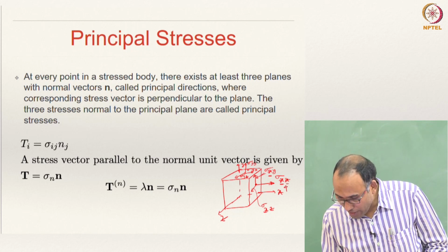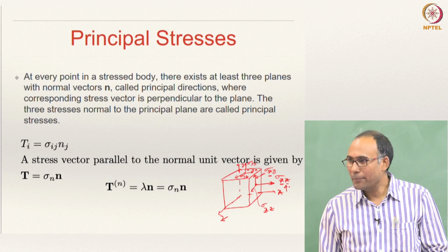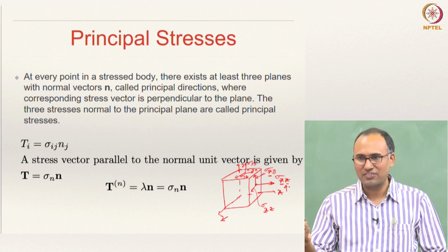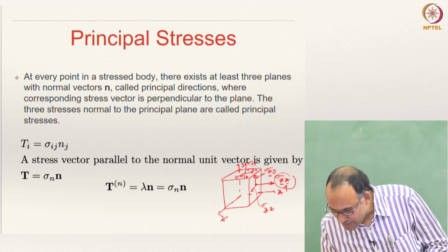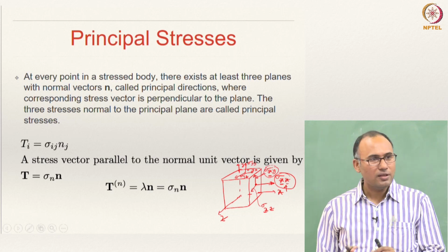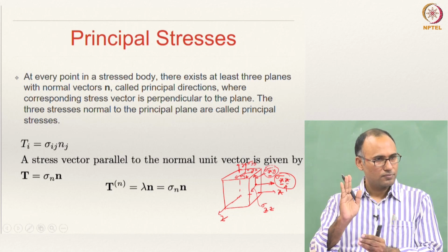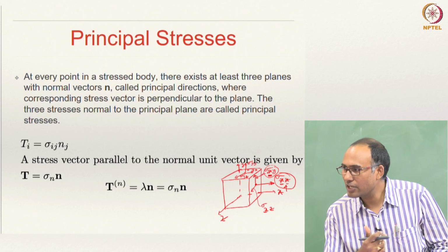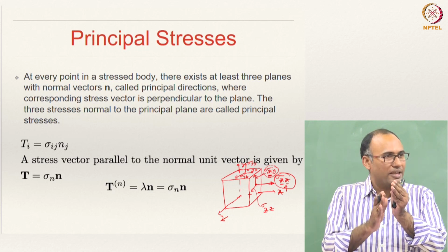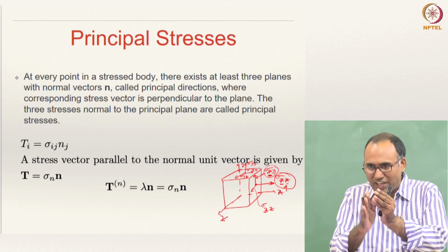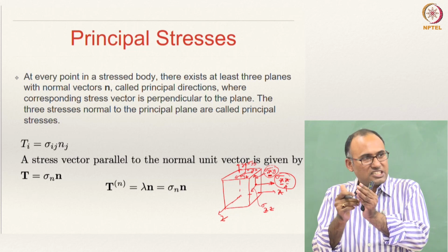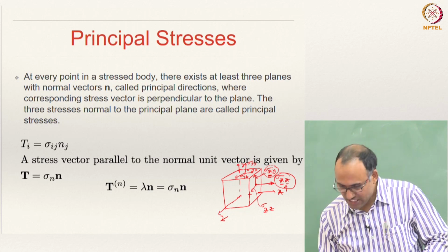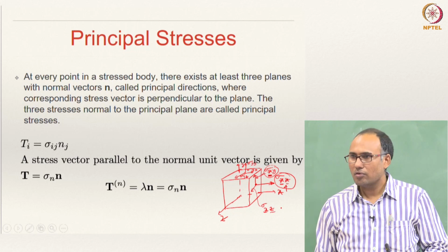So, this is called normal stress component because the direction of that particular stress component is in the direction of the normal itself. That is why it is called normal stress component. And this is shear because it is in the plane. So, the first index x represents the normal, that means it is representing the plane. So, this is basically your plane of action, and the second index is representing the direction in which it is acting, sigma xy, and this is sigma xz, right.